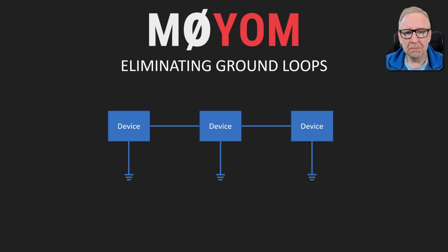It should go without saying, but you should never, ever, ever mess with the electrical safety ground. It's there for a very good reason, to keep you safe. There are even some commercial products out there aimed at the audio market which deliberately break the safety ground. Don't use them, they aren't safe, and your safety isn't worth jeopardising. It can lead to electrical shocks, fires, and injury, and potentially worse. What we can do instead is break the ground on the connection between the devices.